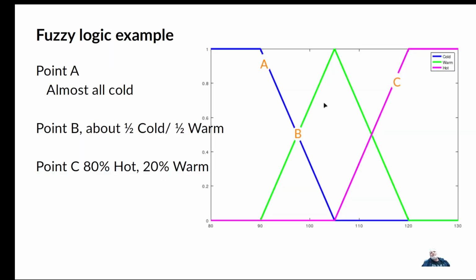Now with the heat box that we're using, you may not want to turn the heat off all the way, because that fan really blows the heat out of there quickly. So you probably don't want to turn the fan on 100%, maybe 50%, unless you're way over here. And again, that's where you could add another fuzzy set, like very hot. At very hot, you probably want to turn it on 100%. But at hot, I would say no more than 50% for the fan.